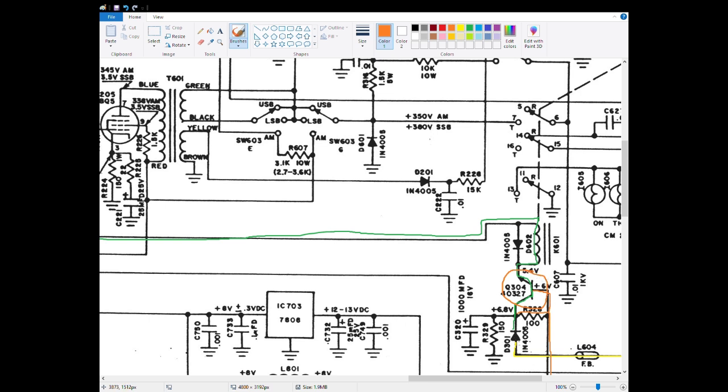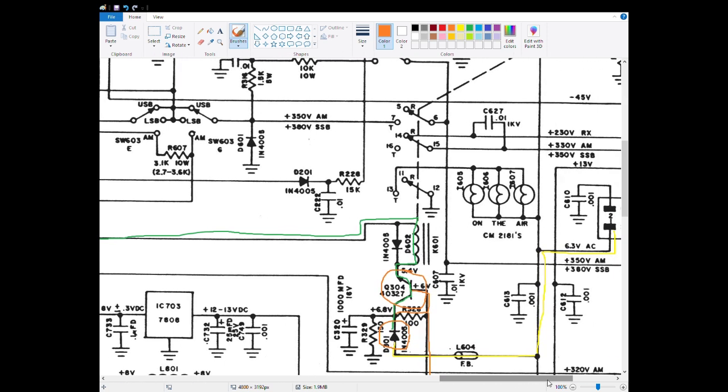So the voltage, about around 6 volts, goes from that through the coil and then looks for the ground, and when you key your microphone, that's when it goes to ground, and that energizes the coil and sucks it shut.